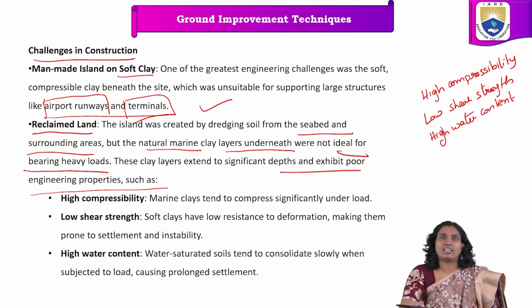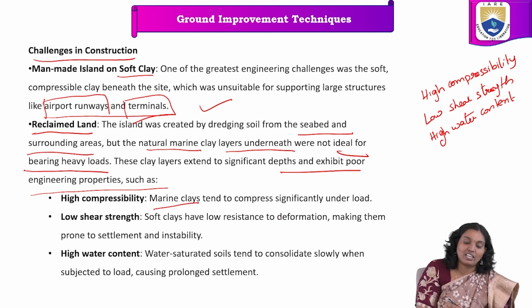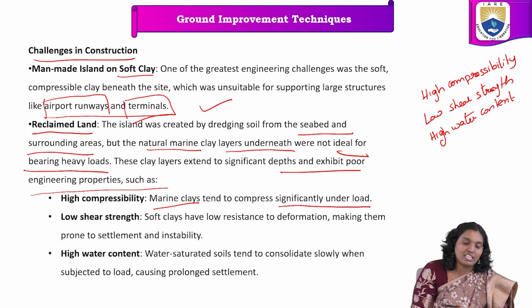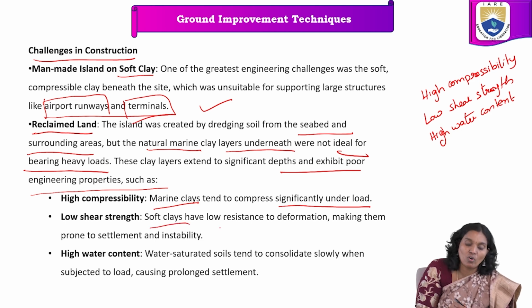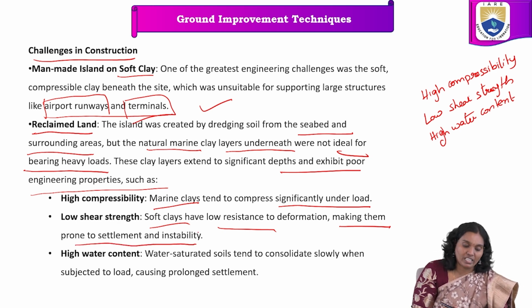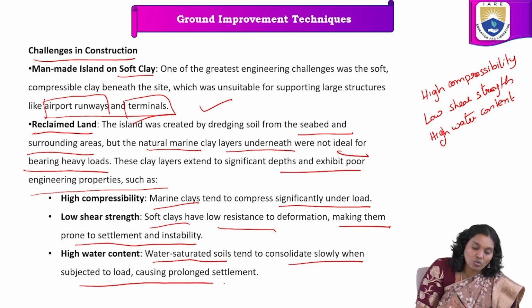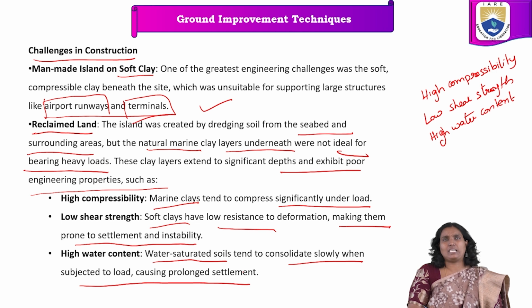High water content. So in high compressibility, marine clays tend to compress significantly under load. In low shear strength, soft clays have low resistance to deformation, making them prone to settlement and instability. High water content: water-saturated soils tend to consolidate slowly when subjected to load, causing prolonged settlement.